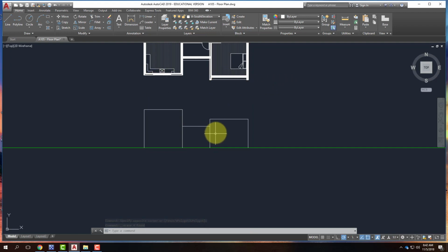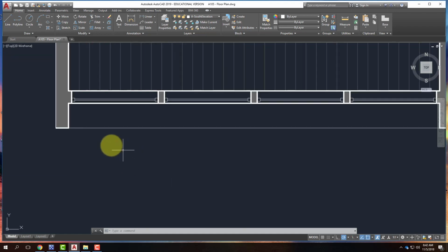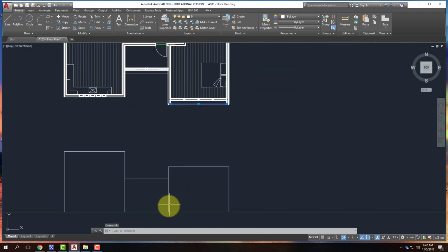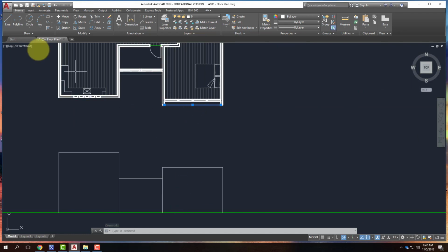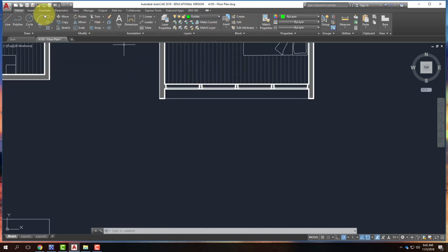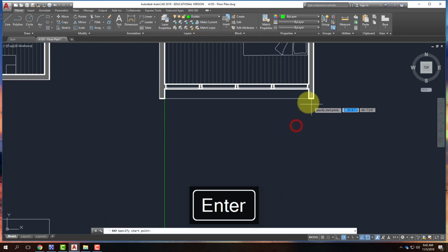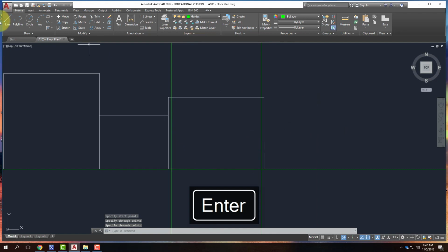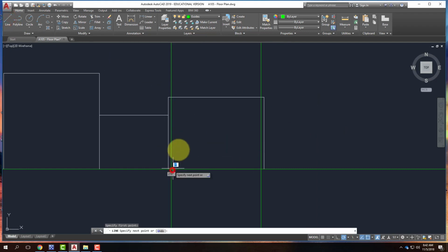There's some other things that are happening. So in this, for example, the walls extend beyond the plane of where the windows are, and there's a little overhang that happens. So I would need to come over here and draw that down here. So once again, I can use the rays to find out where it is. I'm going to switch to my guides layer. I will select ray from the toolbar, or type ray, and I'll pick the inside wall there. I'll repeat my ray and select the inside of that wall. And then I can draw a line that goes up.